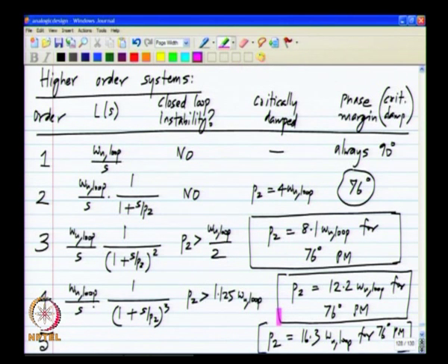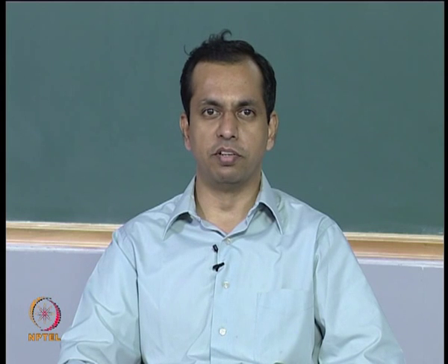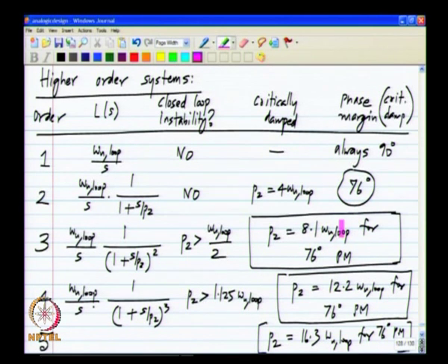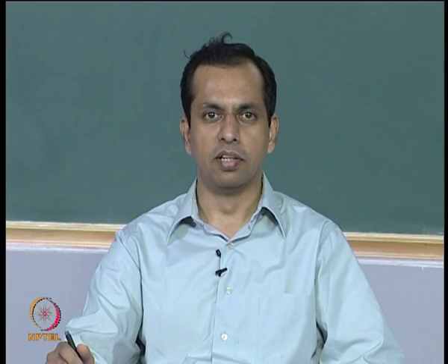So, as you have more and more poles, and we have assumed identical poles, each of those poles has to be further and further away from the unity loop gain frequency. And in fact, you can see that if you think of each pole as adding a delay, here you have a single pole adding a delay of 1/4 the time constant of the integration that is in the loop gain. And here each one has to add approximately 1/8. So, 2 of them combined will add 1/4. Here 3 of them have to add 1/12, and 3 of them combined will be 1/4. Similarly, here 4 extra poles each has to add 1/16, and the combined effect will be 1/4.